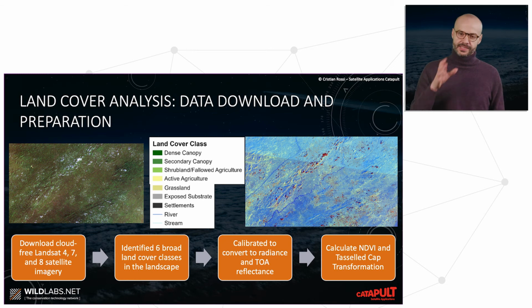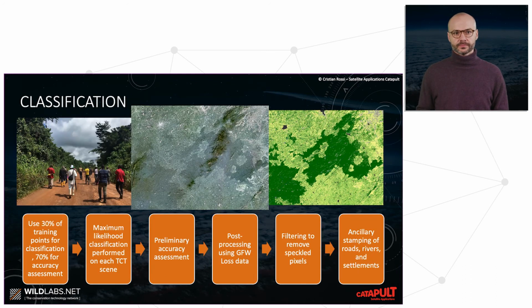And as I explained, a process that is typically done with optical remote sensing is to transform radiance to reflectance, and that's done within this project, alongside calculating different products such as the NDVI, again we can refer to a previous video, and different land cover classes.